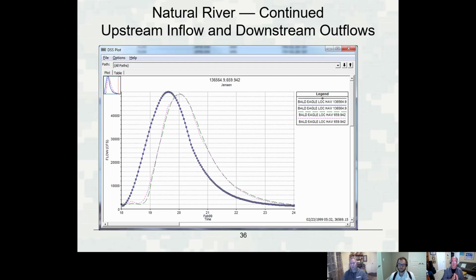I really just need to think about cross sections based on change in water surface and having enough cells. Okay. So it's going to be a slightly different approach. Is the computation of the volume in the 3 subsections going to be based on the respective reach lengths, or is that being pulled out of terrain? So currently it takes the terrain of the faces and then just the reach lengths to get the volume.